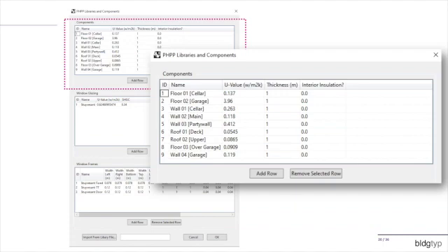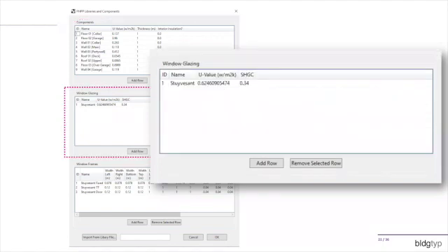And so what we have done here is we allow you to actually import data from PHPP. So if you want to use PHPP to build your assemblies, you can see on the bottom of the screen here, there's an import button. You can basically just point this at a PHPP and all of that data will get pulled in. So you can still use PHPP to essentially build your database there, and then you can always connect it to this. That's all we use that for, opaque assemblies.